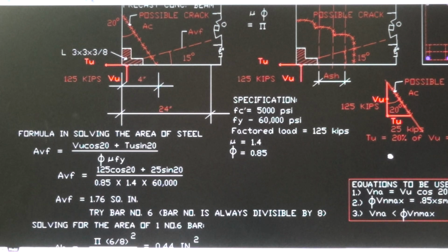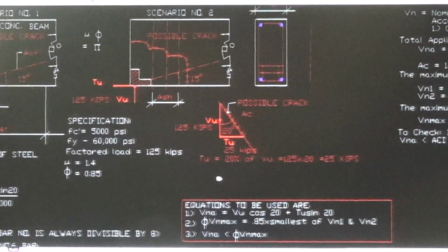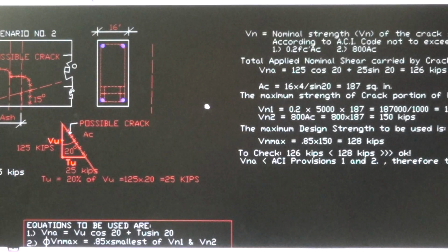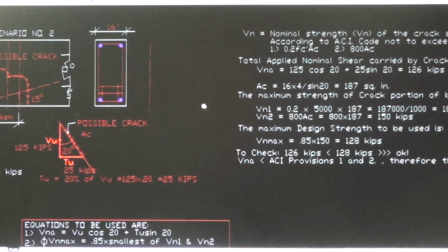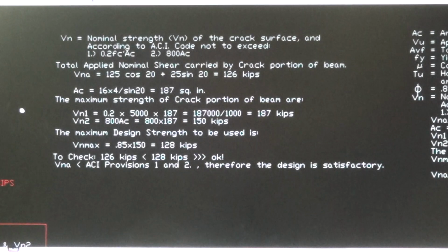Since we're using the applied shear force, this applied shear force should be less than the design strength of the crack portion of the beam.